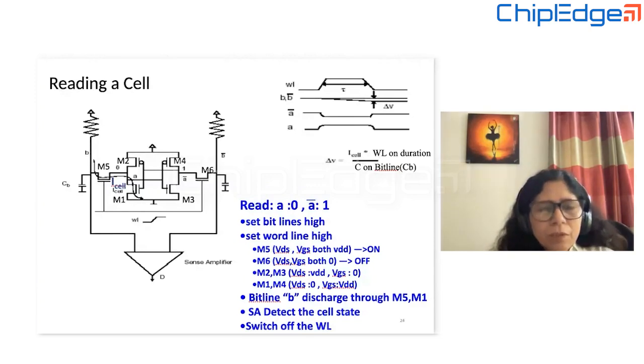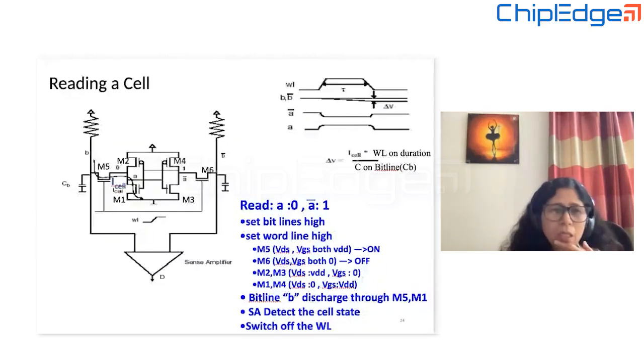What is the PVT condition to get worst case SNM? So worst case SNM, nowadays things have become so tricky that probably one PVT condition will not be the worst case. Depending upon the node, temperature sometimes poses a challenge. A lot of times I have seen we have to simulate in both the temperatures for a given process and voltage.